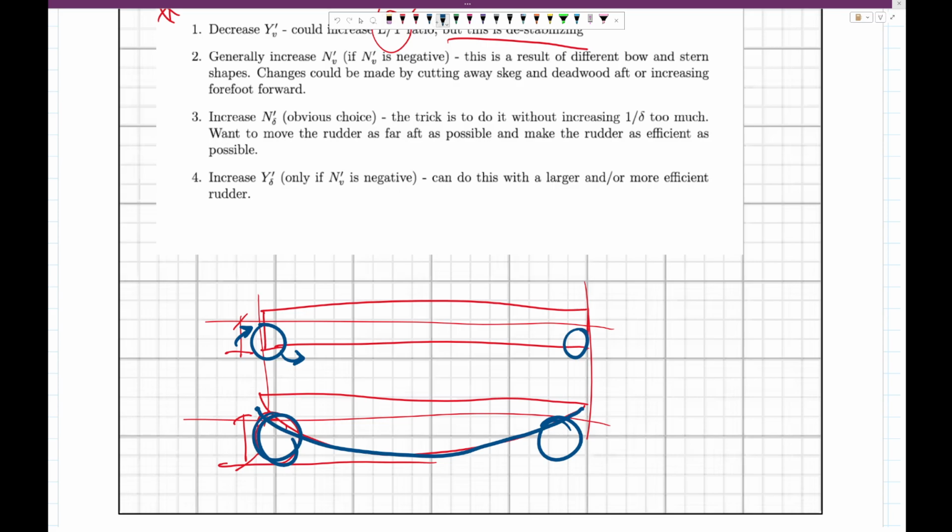You can have a full rocker, which means the entire canoe has a curvature to it, or you can have not a full rocker, where you have just the front and the back curved, and then a flatter midsection. I would recommend the latter option. Usually I've seen canoes with a full rocker, and they are very directionally unstable. Like they just can't go straight, ever. So I would recommend having some type of flat section.